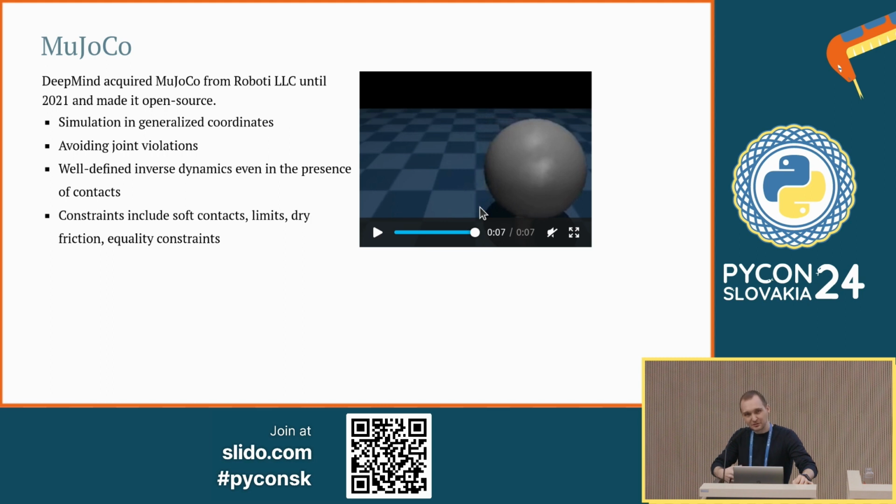So the advantage of MuJoCo is that it's fairly well contained. It's not as complete as SOFA, but it lets you simulate things fairly well, especially if you're simulating objects with joints and contacts. So for example, like a robot walking in a room. It's touching the ground, it's making contacts, and you want to see whether it's stable enough.